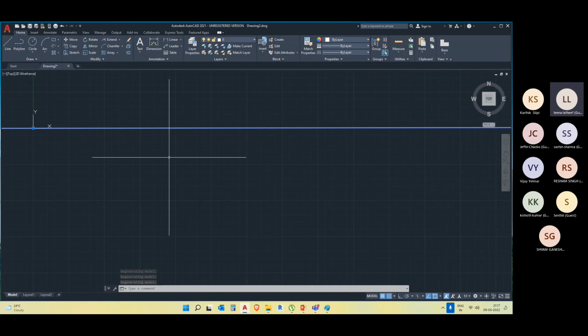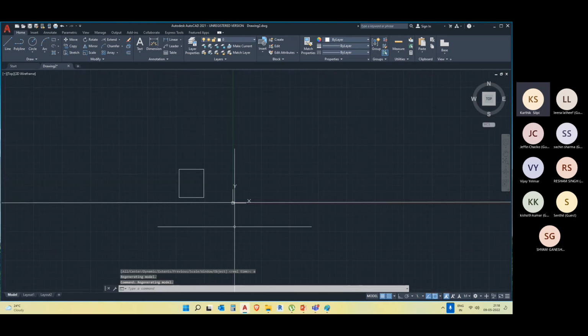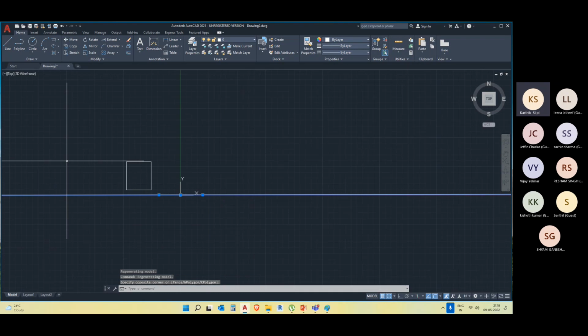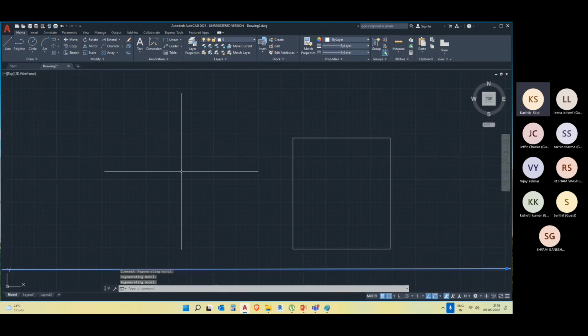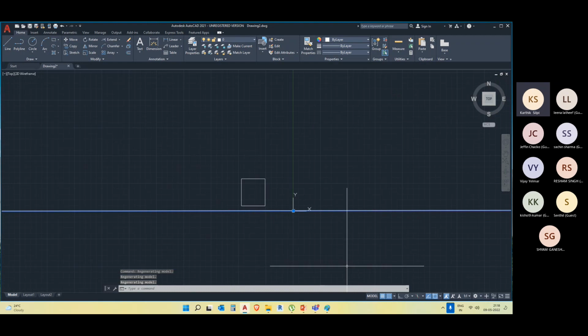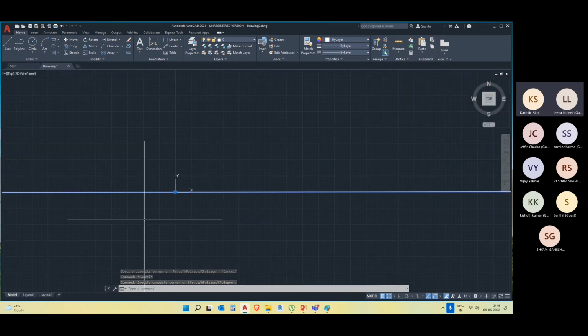Okay. So here, this is an example of our Z enter E enter. I just quickly press Z enter E enter, and you'll have your drawing at that place. The use of the construction line is that these are your grid lines or just reference lines, which are unlimited, and also used for reference whenever we are drawing large projects. This is also useful in small projects. You want your reference line, and this will not be confused because this is a big line.